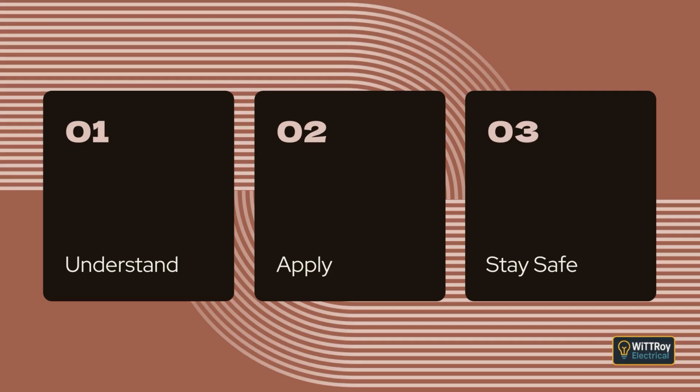Clause 3.9 Installation requirements. This clause introduces the general rules for how wiring systems must be installed so they remain safe under normal use, wear and tear, and any unusual conditions that can reasonably occur. Clause 3.9.1 General. Wiring systems must be installed following recognized safe practices. They must be installed in a way that protects the installation against mechanical or electrical failure, both during normal operation and under conditions that may arise over time.